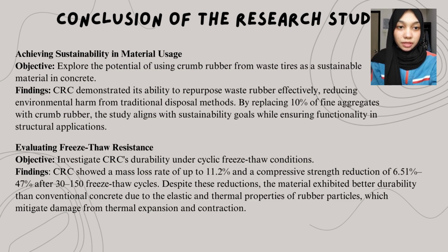Evaluating freeze-thaw resistance. Objective: investigate CRC's durability under cyclic freeze-thaw conditions. CRC showed a mass loss rate up to 11.2%, and a compressive strength reduction of 6.51% up to 47% after 13 up to 115 freeze-thaw cycles.